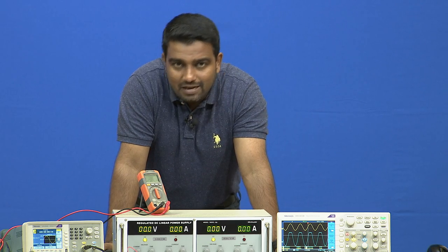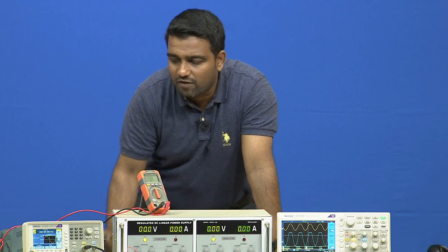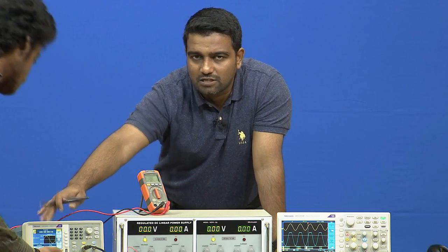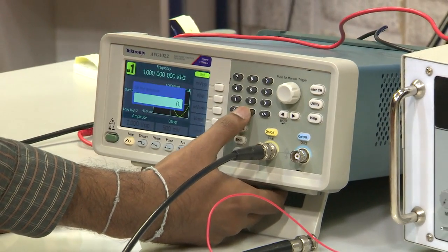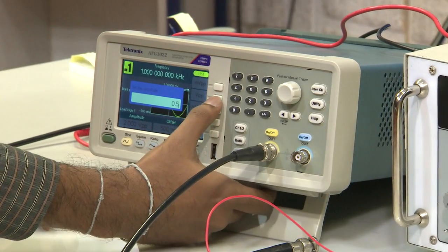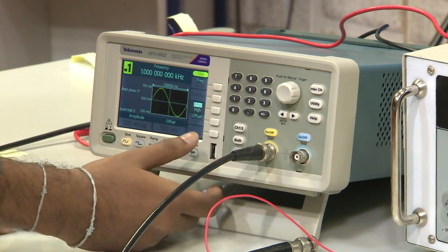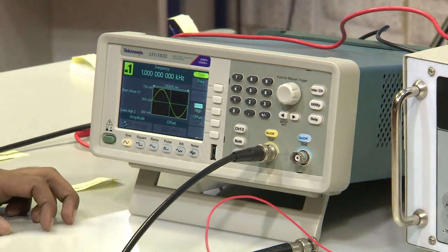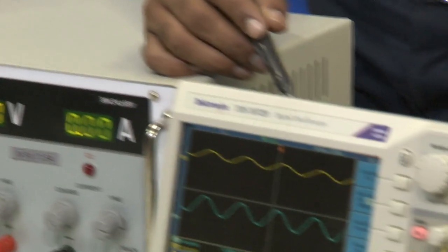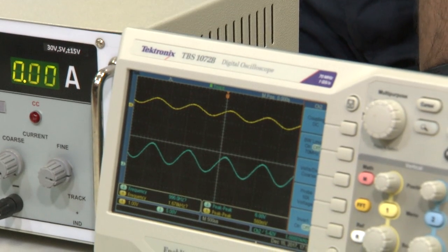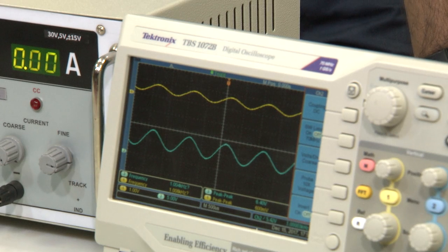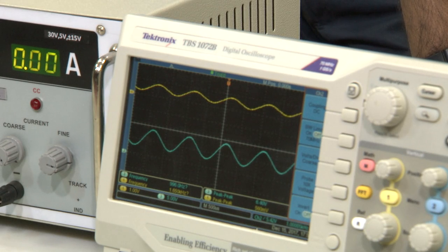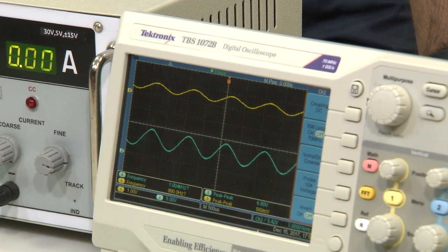But what if we decrease it? So, if we can quickly decrease the voltage here in the input, let us say we are applying about 0.5 volts peak to peak, that will give us an output which we can see here in the oscilloscope, right. So, it has amplified about 11 times. 11 times 0.5 would be around 5.5, right. But what you can see is about 6 point something volts actual.